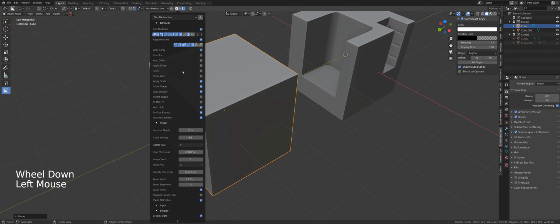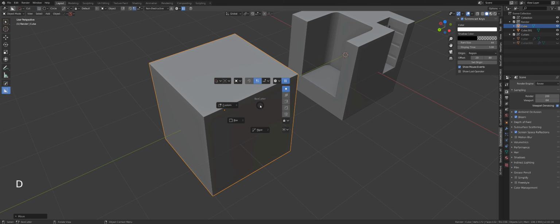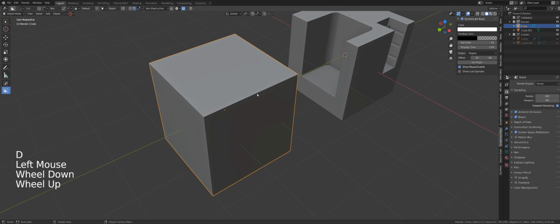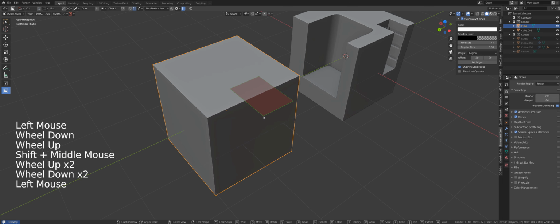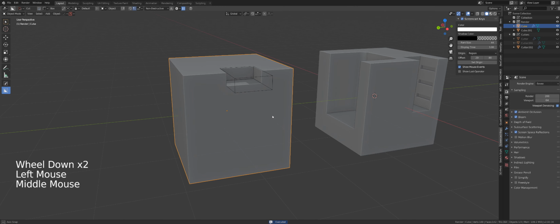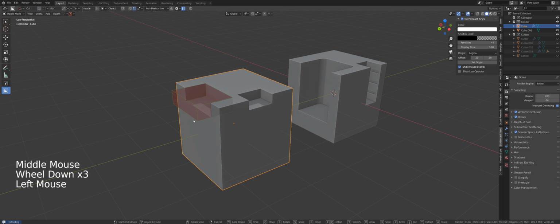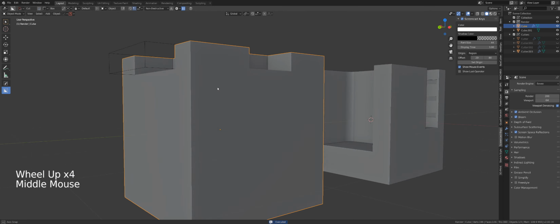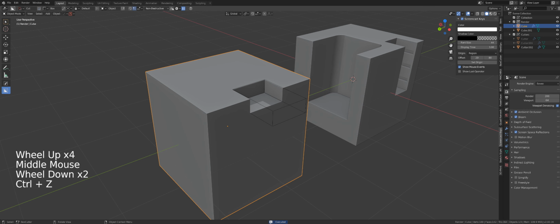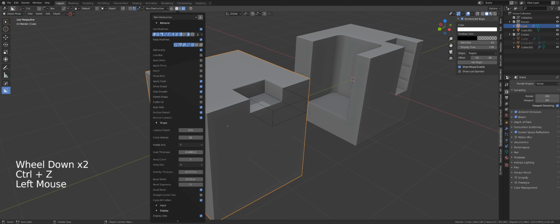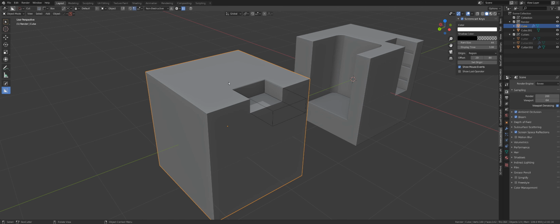So if you go to options, well, let's go first without options. Let's say that I want to cut to this depth, okay? But I want every single cut that I perform to be at the same depth. So instead of eyeballing this, what you can do is go to the shape function and change the value for the laser cut to, let's say, 0.2.